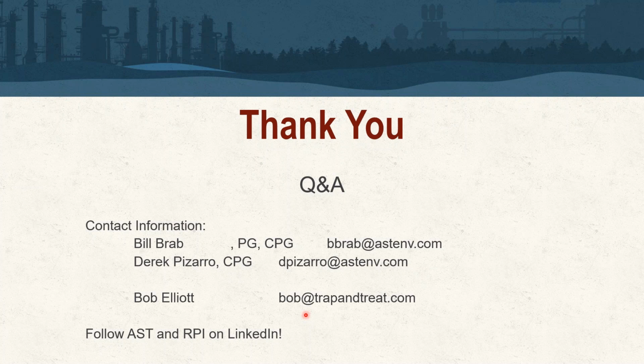And as we've noted before, the well construction, or the specification that we need, are open boreholes for our particular purpose. So for the characterization, we want to be able to insert tools within that borehole, whether it be geophysical tools, downhole camera, or this packer assembly for the purpose of aquifer characterization and analytical testing.